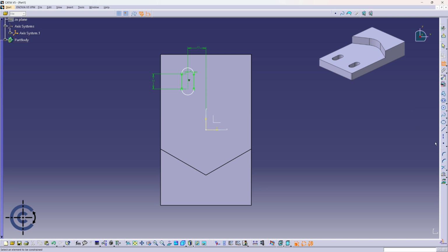So instead what we can do is click point. If we hover over the line, you'll see that the blue circle next to my cursor is hollow. If I drag down, it will snap to that circle. If I drag down a bit further, you see it's now a pinpointed hole. That means it's snapping onto the center. If I click, that point is now at the center of my line.